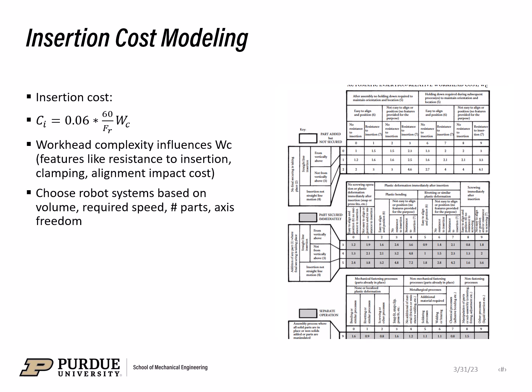Okay, so to summarize everything from the cost model, we looked at how machine architecture, part design, and mathematical modeling all influence assembly cost and feasibility, but what's more important is how these interact. For example, a part that is cheap to produce but expensive to feed might not be worth it. And conversely, a higher cost part that simplifies insertion and orientation might end up justifying its expense.